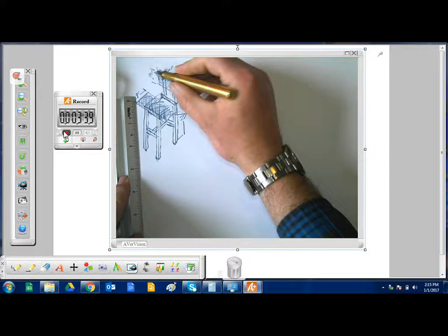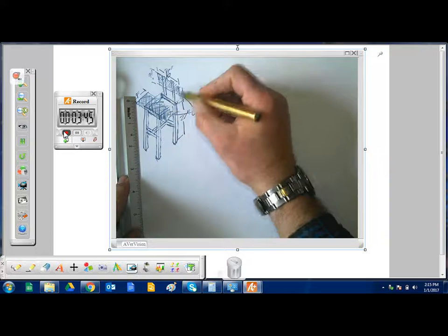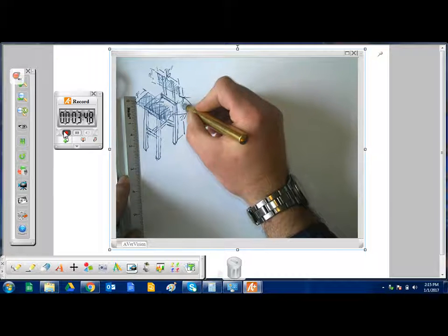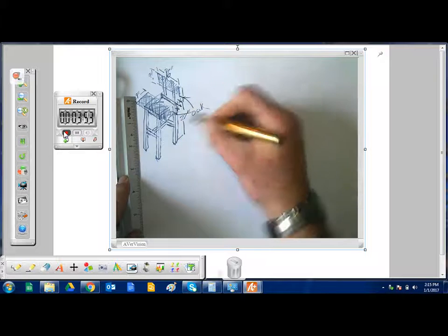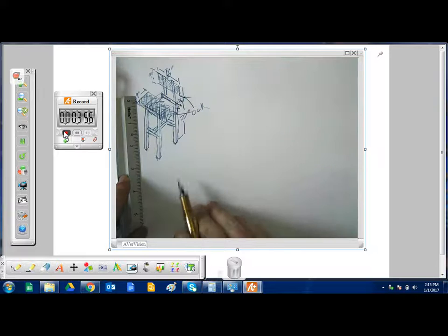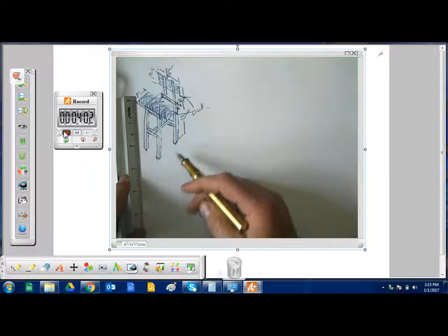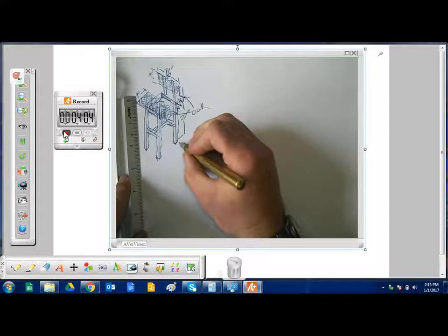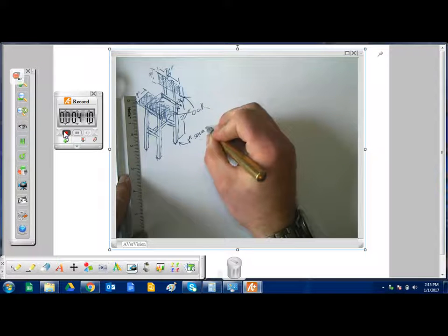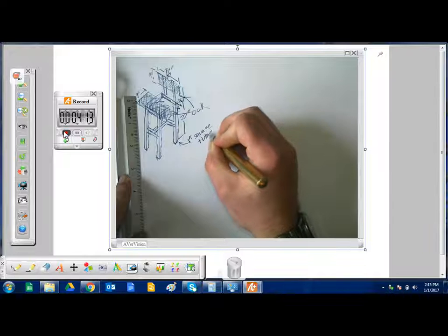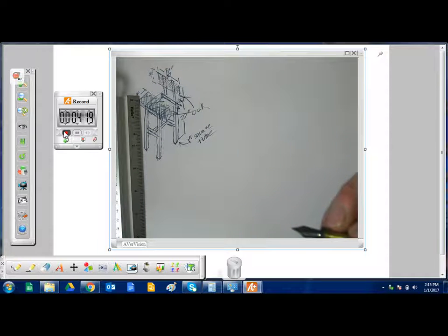I did similar find out here, so I believe this is actually not a question mark, this is actually I think 16 inches. So I've got a 16-inch wide backrest and seat, and then this dimension from here to here, that is still X. And from there to there, that is still X. This thing's starting to get a little cockeyed, so I'll probably need to do a few more drawings there. 27 inches from the feet to the seat, and we're going to make it out of oak, and let's go and make a notation here. 1-inch square tube.